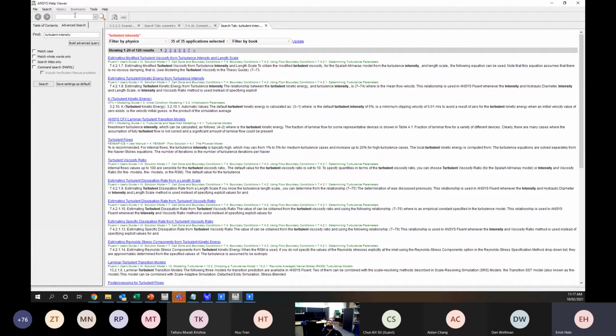Also, like I said, in the case that I built with an ABL, an atmospheric boundary layer, there are specifications in the standards that tell you what turbulence intensity should be seen at each level, and level being the distance from the ground plane. And for a wind tunnel, we know that the turbulence intensity should be around 1% or lower. So yeah, it's case specific, and there's not necessarily going to be easy answers for it. I would be looking at research. If you can't find it in the help files, going towards research and other people's simulations before moving forward.